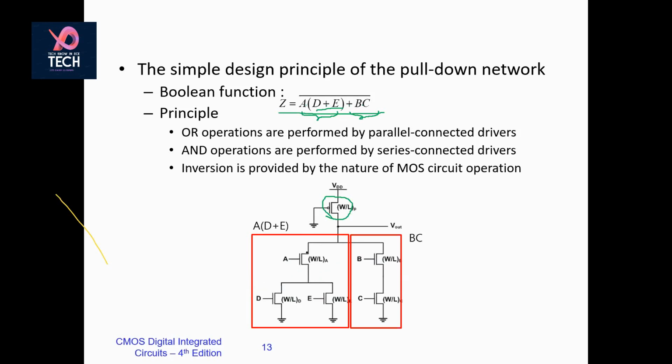So to avoid delay, the operation with the least activity will be put on the top, while operation with the most activity will be on the bottom, so that we are avoiding the overall delay in between, because some charge is being required to these parasitic capacitance of these transistors also. So that is the reason the maximum operations are at the bottom, least operations will be at the top. Now, this is how we have actually designed your pull down network.